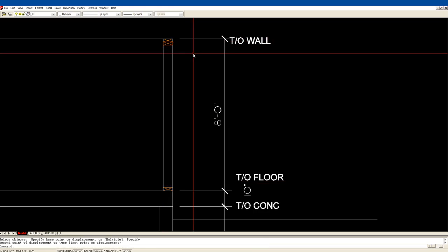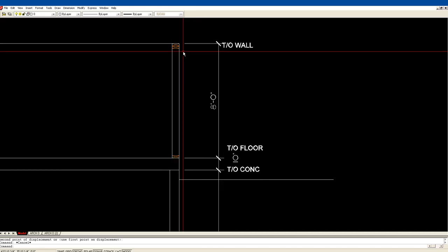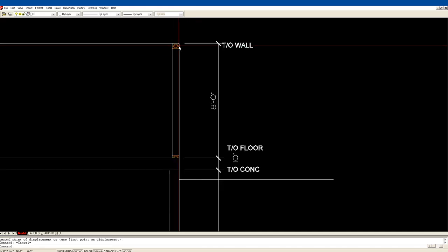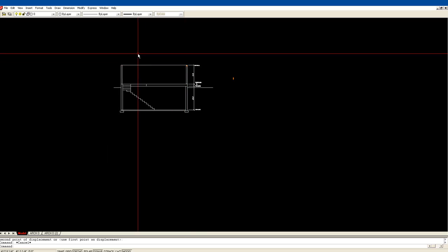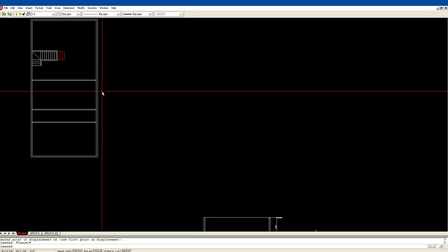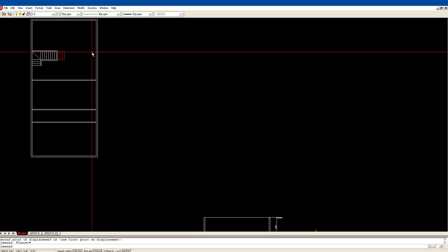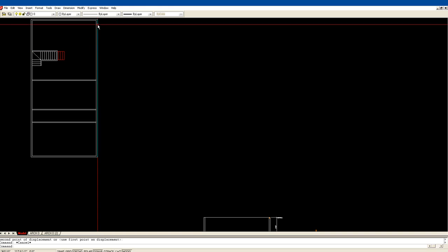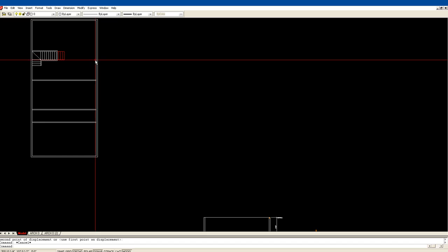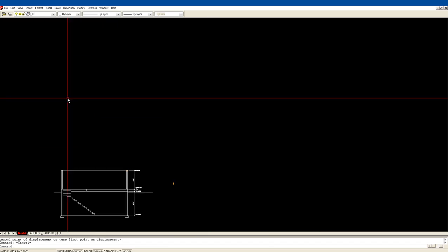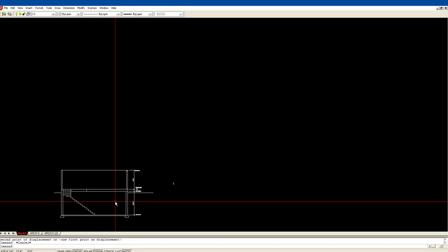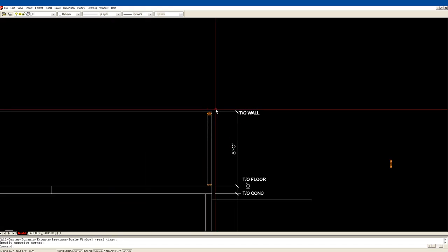Again, this is a cross section of the wall. So we have two plates at the top. Typically, when they're building this long wall here, which is the one that I'm showing the cross section of, they won't build it 58 feet long and try to stand it up. They'll build it in sections, maybe break it into 3 sections, depending on how much manpower they have. They will join the sections together with what we call a locking plate at the very top.